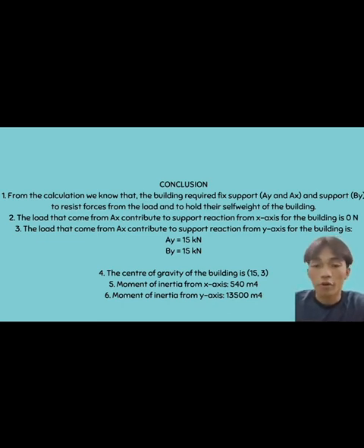The load that comes from Ax contributes to support reaction from the x-axis for the building, which is 0 Newton. The load that comes from Ay contributes to support reaction from the y-axis for the building, which is Ay 15 kilonewton, and By is also 15 kilonewton, as you can see from the slide before.